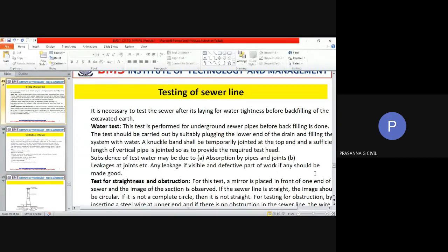So every sewer pipe length will have one end plain and the other end cast as a wide flange. The plain end of one pipe will be inserted into the wide end of the other, and the space in between the two will be tightened and made watertight.